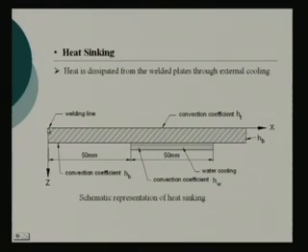Say here is the other half of the plate that is extended on that side, say a butt welding is being done or a stiffener is being welded here. So, heat will flow along the plate. If I put a heat sink here, schematically I am showing a situation of water cooling. Water cooling means heat sinking, means heat is flowing here and going into the water which is flowing below, the heat is taken out, right.